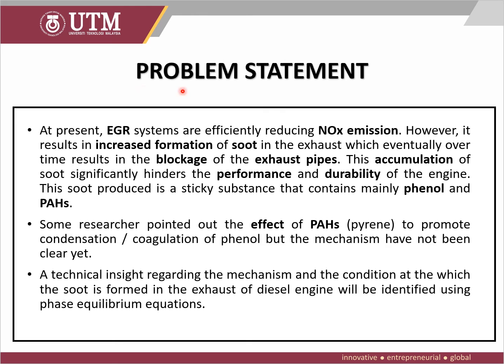Next, for the problem statement of this project. At present, EGR systems are efficiently reducing NOx emission. However, it results in increased formation of soot in the exhaust, which eventually over time results in the blockage of the exhaust pipe. This accumulation of soot significantly hinders the performance and durability of the engine. This soot produced is a sticky substance that contains mainly phenol and PAH.